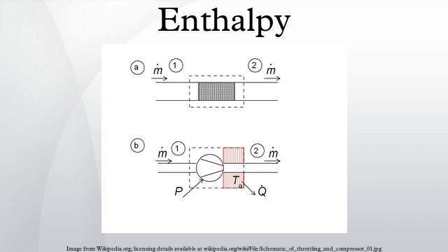If we allow also the system boundary to move, we get a rather general form of the first law for open systems. In terms of time derivatives it reads: where the sums represent algebraic sums and the indices k refer to the various places where heat is supplied, matter flows into the system, and boundaries are moving. The terms represent enthalpy flows, which can be written as with the mass flow and the molar flow at position k respectively.